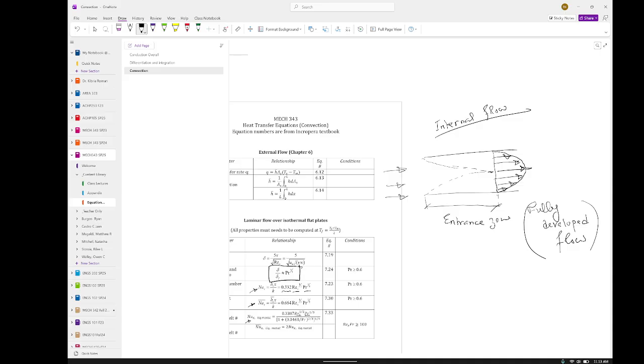Internal flow, it doesn't. So that's why what you'll be doing, you first find the Reynolds number for internal flow, and if you find it crosses 2300, that means it is turbulent all over the place. Does it make sense? Unlike the external flow where you have the mixture of laminar and turbulent, you don't have that. You just have turbulent now. If it's more than 2300, or 3000 to be on the safe side. If it's less than that, it's laminar only inside. Okay? So there's a clear distinction between external and internal flow.